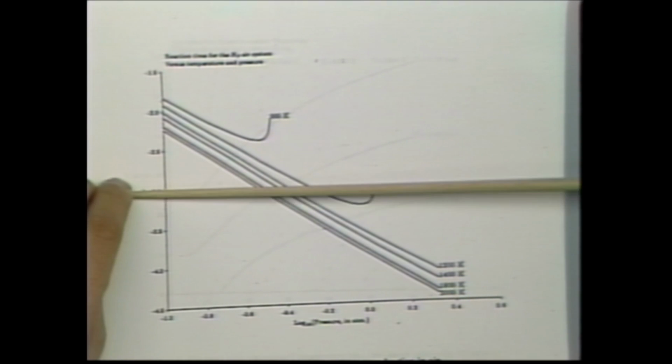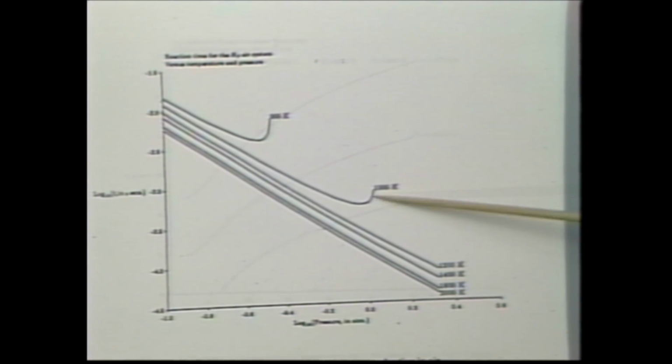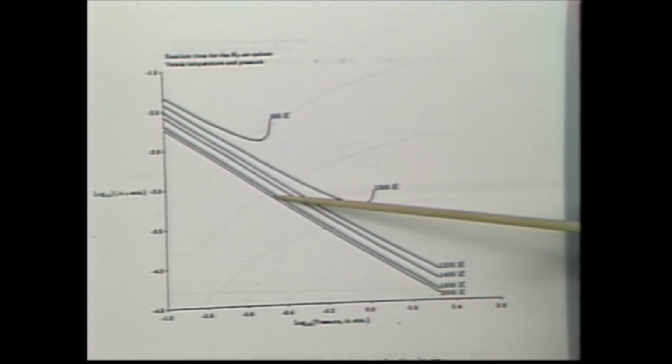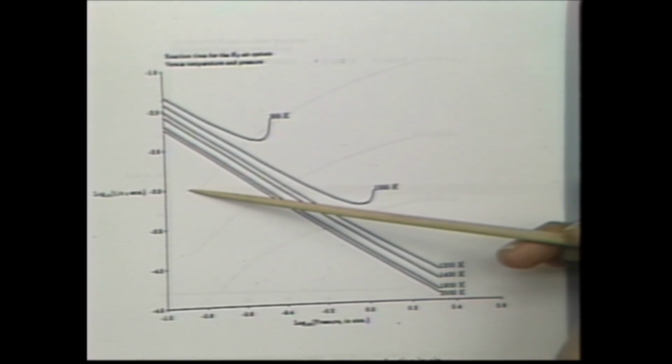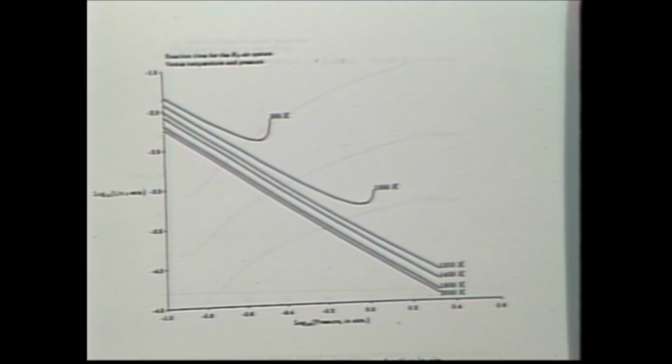That tells us if we've got flow coming into the engine at about 1,000 degrees, or 1,500 degrees in that range, we have to be somewhere at some reasonable fraction of an atmosphere in pressure in order for that fuel to burn fast enough inside the engine. If we go with a lower pressure system, then we simply won't get reaction at a sufficiently rapid rate to be able to design a reasonable engine. So that means that the propulsion system depends on the inlet supplying flow at the right temperature and the right pressure, or the combustion simply won't work.